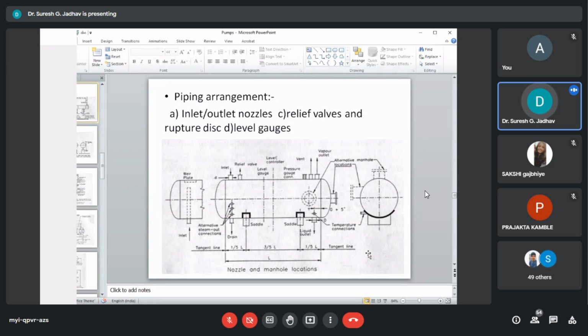In a reactor, the manhole should be oriented towards the axis to facilitate the manual feed if required. The utility manifold and the process inlet manifold should be placed at the operating level irrespective of the nozzle attached to the vessels. Piping should run overhead, as short and as simple as possible.